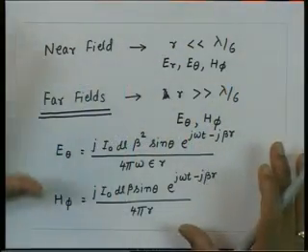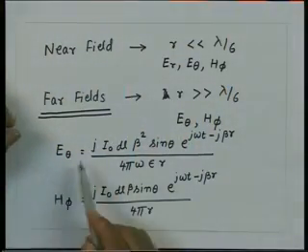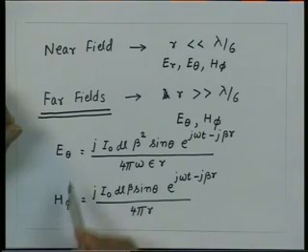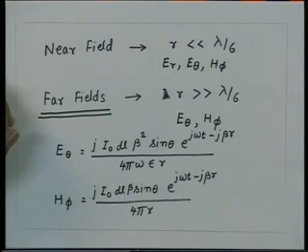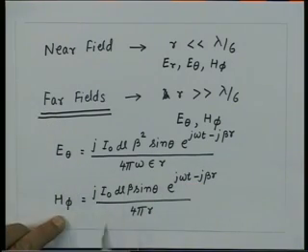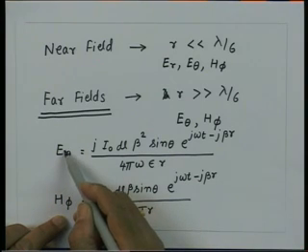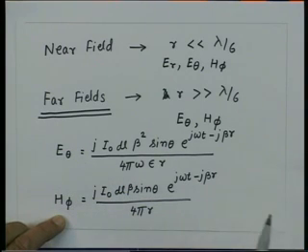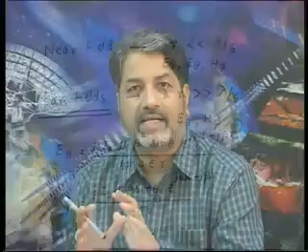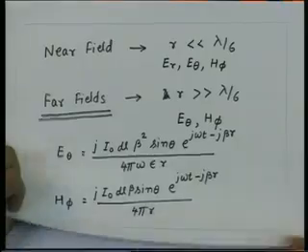So all these constants which you are having here, I0, dl, beta square, all these quantities are now taken as constant, because we are interested only in the relative variation of the electric field as a function of theta, and the same is true for phi for the radiation field, because the ratio of E and H is equal to the intrinsic impedance, that is constant. That means the radiation pattern which we get for electric and magnetic fields is exactly identical. So since we are now interested only in the relative fields, these factors do not matter.